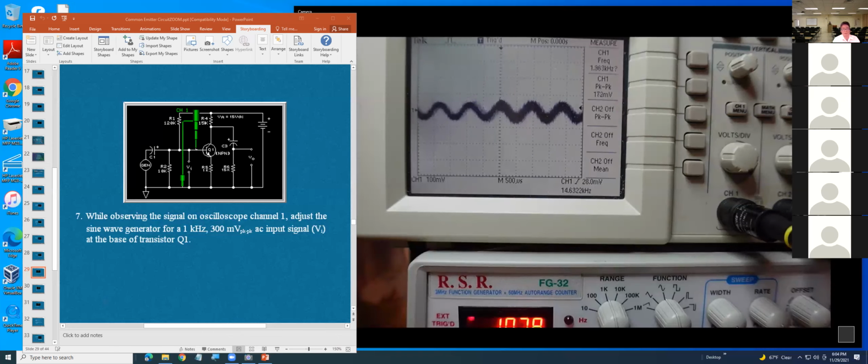So in order to do that, first thing, would you adjust the trigger at all? What do you mean, the trigger? That is already displaying the signal. You can see it as stable as possible. Any trigger, they don't make any difference. The signal is too noisy, so in order to get the value, you must use the cursor.